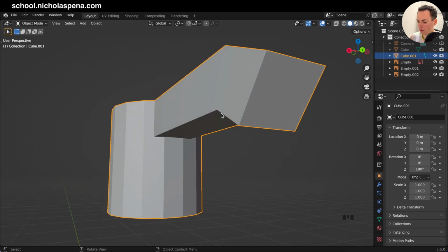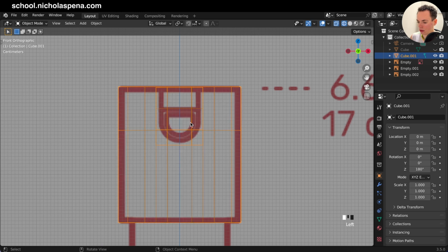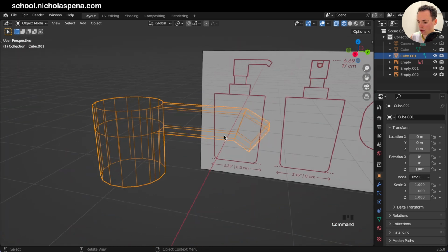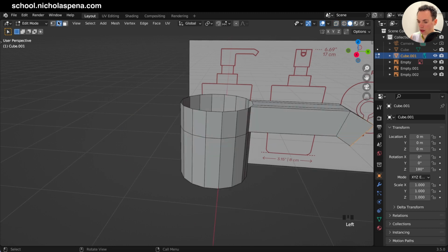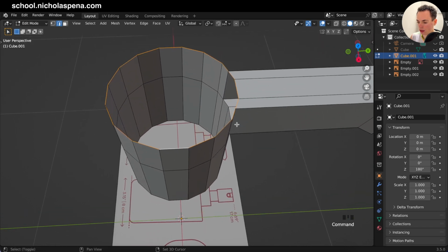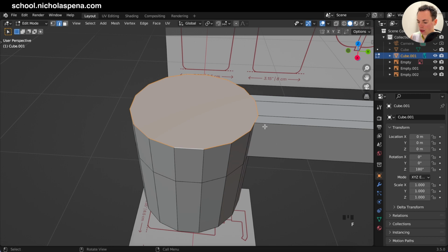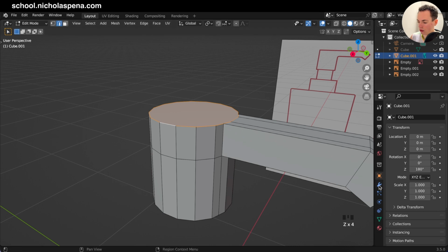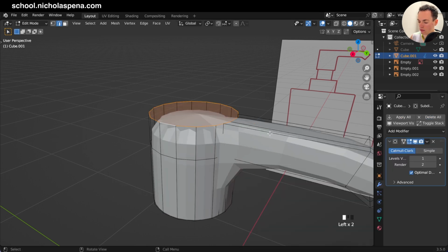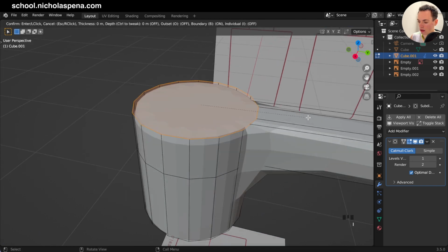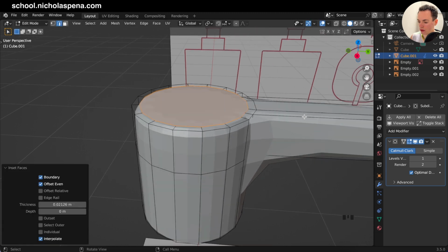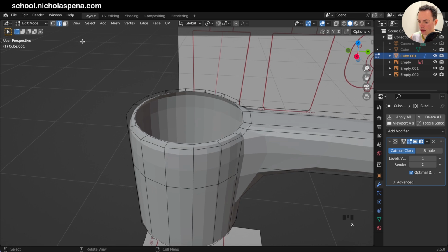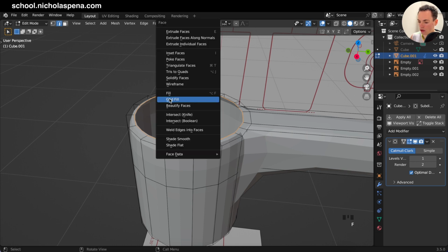We need to create a shape here like this. First, we can edge select, get these, and then create a face, F. Then we are going to inset, because we are going to put a subdivision. So first we can put the subdivision in the modifier. Subdivision is going to look like this. So I inset, put more geometry on this, and then X, delete the face, and then we can fill the face with a grid. Alt click this, Control F, grid fill, like this.